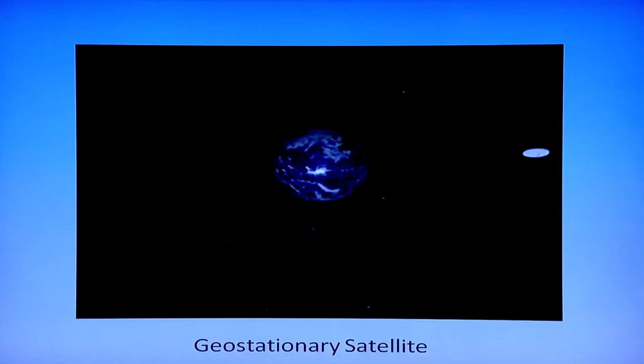that is 24 hours. As you can see on the screen, the satellite appears to be at a fixed position to an observer on Earth. It can keep looking at the same spot on Earth for a very long time, monitor the changes and transmit the data to the ground station. Thus, to direct antennas toward the satellite to receive the signal, one does not have to keep tracking a moving satellite. That would have demanded more expensive instruments on the ground for direct TV transmission.